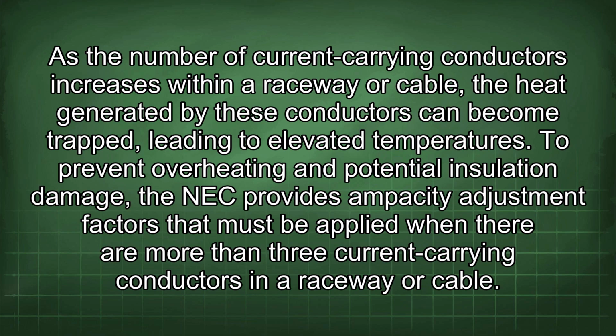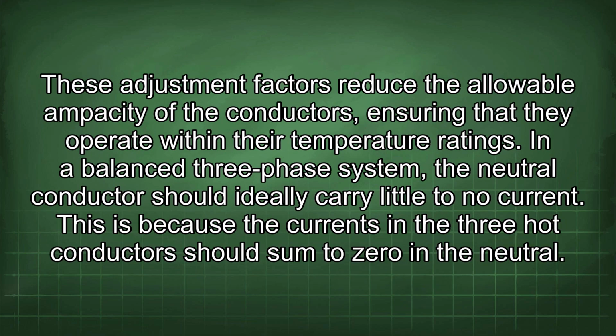To prevent overheating and potential insulation damage, the NEC provides ampacity adjustment factors that must be applied when there are more than 3 current-carrying conductors in a raceway or cable. These adjustment factors reduce the allowable ampacity of the conductors, ensuring that they operate within their temperature ratings.